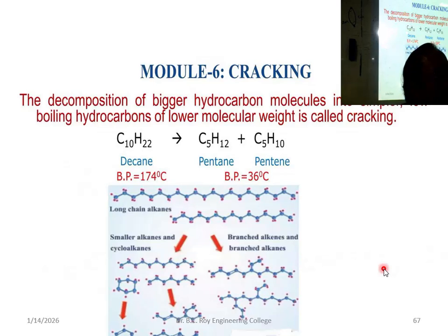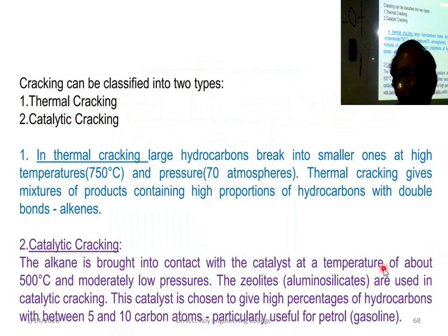Is the concept clear? In one case, the catalytic bed is fixed and the vapor is passing through and cracking is going on. That is called fixed bed catalysis. Another one is fluidization of the bed. The small catalytic particles are flowing and from the opposite direction, the vapor comes in. There is a counter current interaction and cracking taking place. That is cracking.